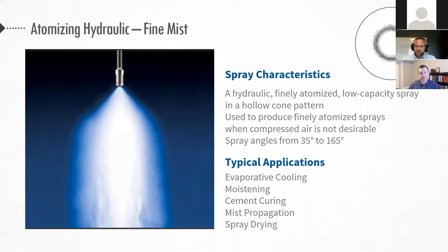That 10 to 100 range, some of our larger capacity nozzles can still form a pattern down to 3 psi. However, that can be very large flows as well, but it definitely depends on the application. Yeah, that's a great question. Kind of on that same line of thinking, how much hydraulic pressure do you think is required to fully atomize a Newtonian fluid at water-like viscosity?